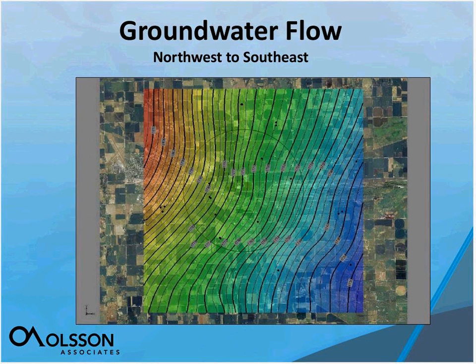In developing the groundwater model, we had to take into account, of course, the groundwater flow patterns across the area. So we took water level data from points, these black points, again, are monitoring wells, across here. Here's our 3-mile radius around our modeled area. This is just an illustration of the water table map across the area. It's going from high, meaning red. Red is the higher water table, to low. So the groundwater flow direction is from the northwest to the southeast.